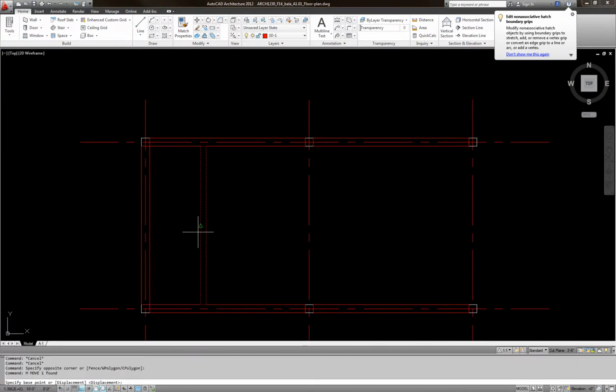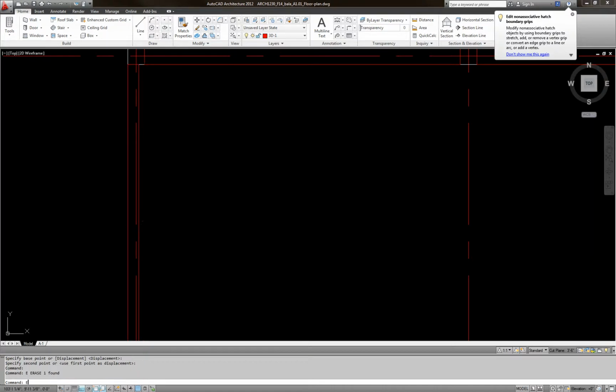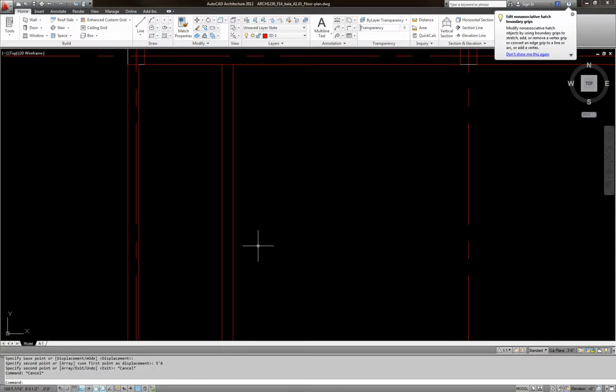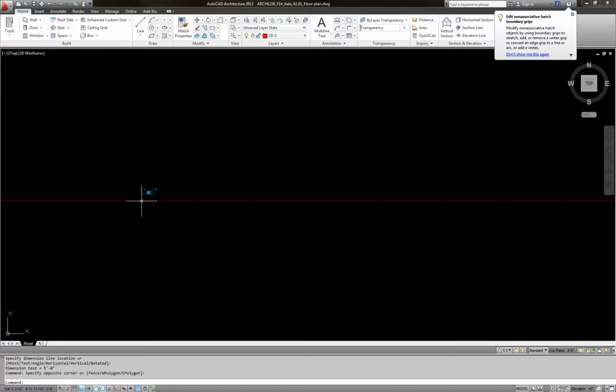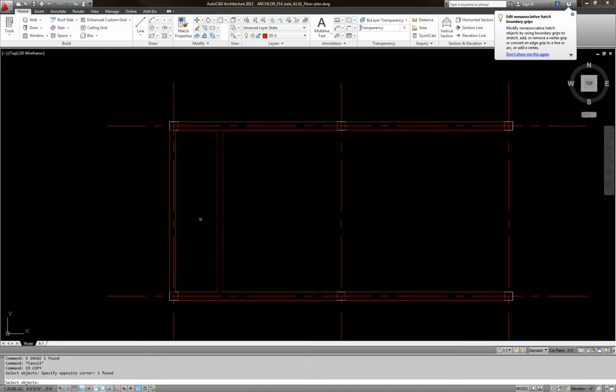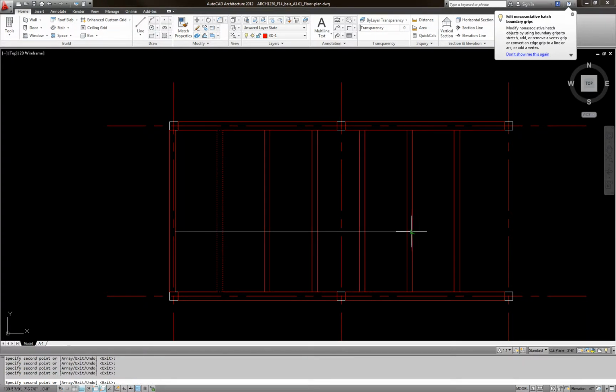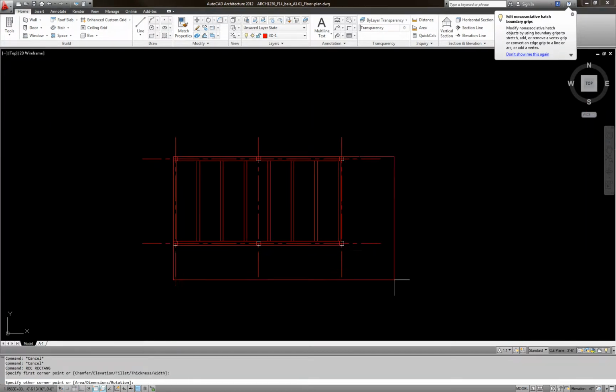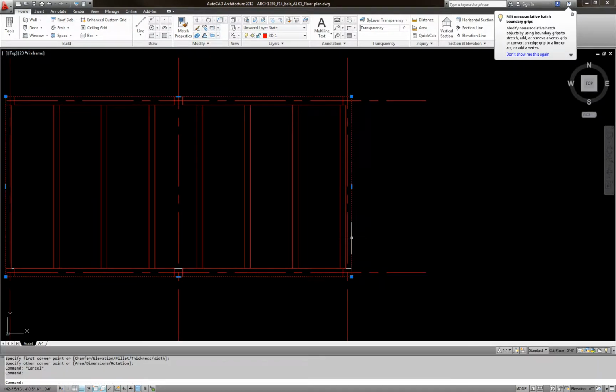And again I want to move this to this corner over here, delete this, copy this 5 feet, 5 feet 8 inches. So if I look inside, I should have 5 feet minimum. They say 6 feet, but in this case I'm just going to use 5 feet, and I'm going to copy this all the way. That's my one-way joist. And also I'm going to put my floor slab here, rectangle REC enter, and I'm going to move this so that it's easy to see the floor slab cutting through this.